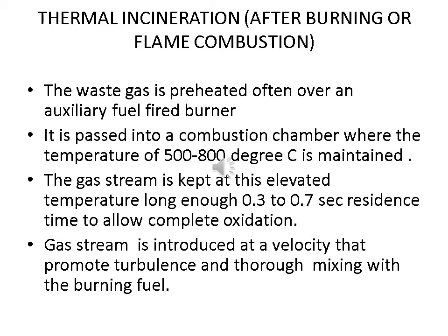The time duration, that is 0.3 to 0.7 second residence time. So this 500 to 800 degrees Celsius temperature is maintained in the chamber. We are going to allow these polluted gases to pass inside this chamber. The duration is 0.3 to 0.7 seconds.